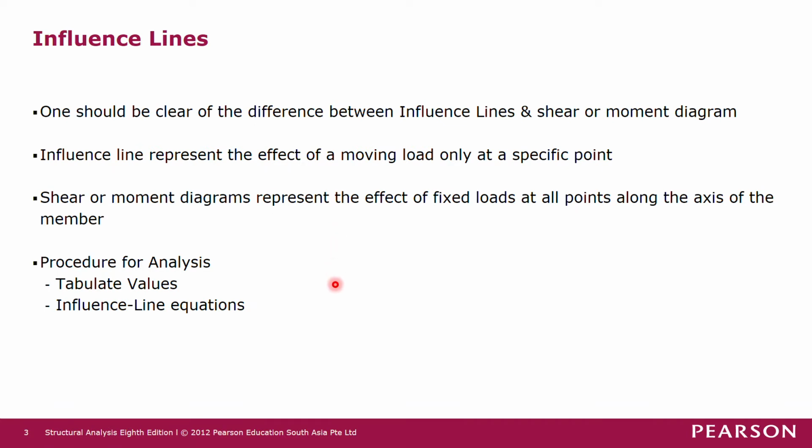One should be clear of the difference between influence lines and shear or moment diagrams. An influence line will look like a shear or bending moment diagram, but they are different. Influence lines represent the effect of a moving load only at a specific point. So in influence lines, the loads are not static. They are moving from one point to another.